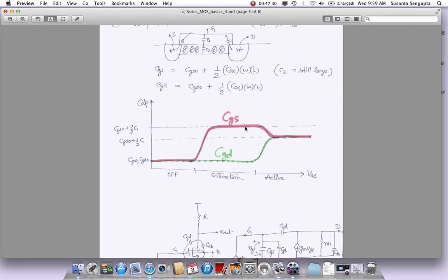So wherever you're trying to design high frequency RF circuits, you are trying to see what the CGS is. CGS is not so much in your control. It depends on what device size you're using, what the W and Ls are. You need certain W and Ls to carry some current, to get some GM, and that puts a limitation on how much CGS you can get, and in a way it limits how fast that circuit can operate. What is the highest frequency it can tolerate?